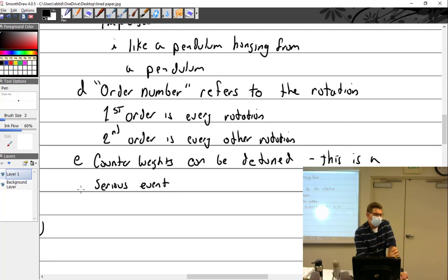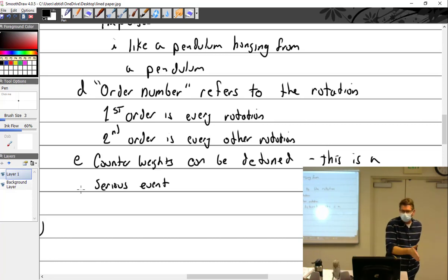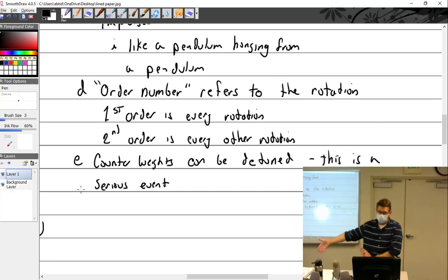And so what you get is a prop strike, and a prop strike used to not be defined as anything. You call it what you want, but through my career, I saw it defined as anything that requires the propeller to be removed for repair. Then that is a prop strike, and the engine must then be completely disassembled, inspected, repaired, put back together. Not overhauled, but a prop strike inspection, which is what I did the majority of my career, I would say.